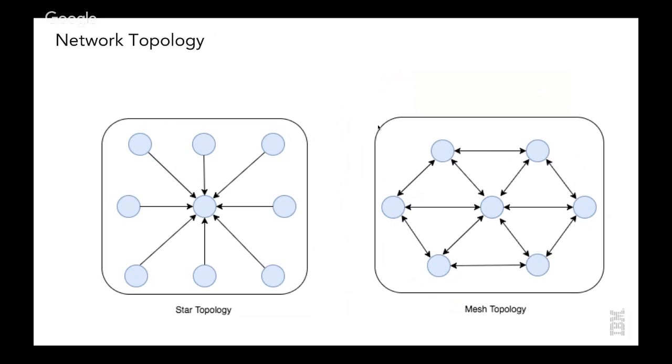So essentially, I chose not to go with Zigbee or Bluetooth because they're short range. The range could be extended because they're based on a mesh network topology, meaning all data is routed from one node to another rather than each node sending the data to a central gateway. I thought it sounded like a cool concept, but it was just very complex. Also, I was expecting my devices to go into deep sleep mode throughout the day and just wake up when they were needed in order to extend battery life.